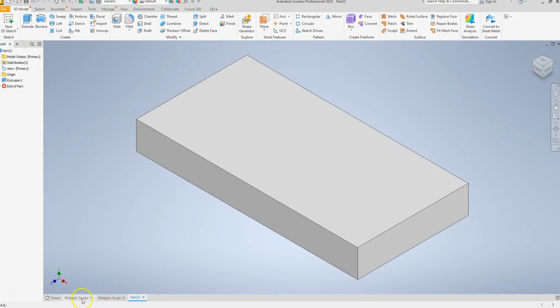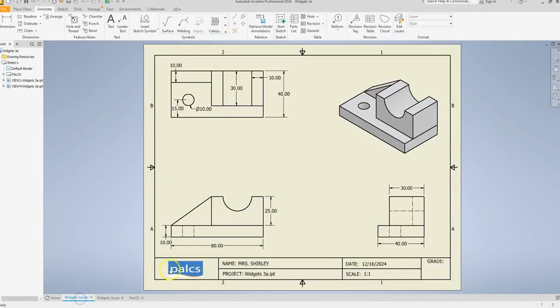Click OK, and we have our base of our object. So let's move on, and let's create this part here. So we are going to use the subtractive method. We are first going to make a cube to put on top of our base, and then we will subtract out the sloped area here that we see in the middle.